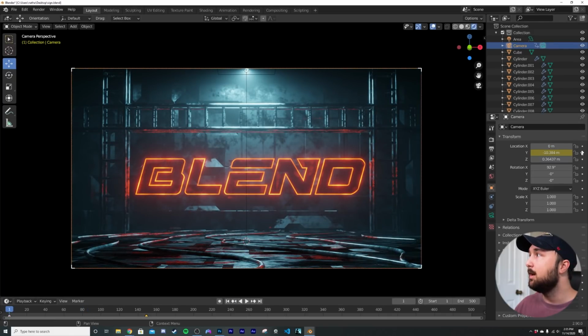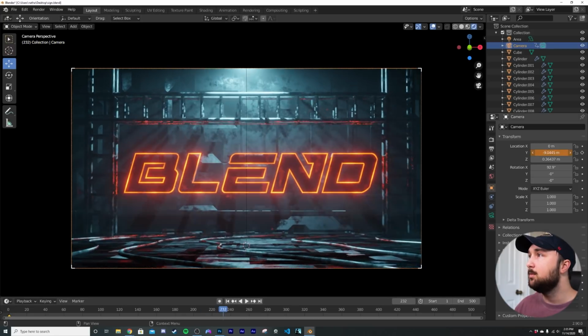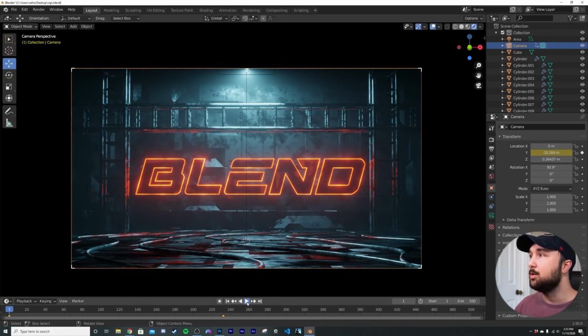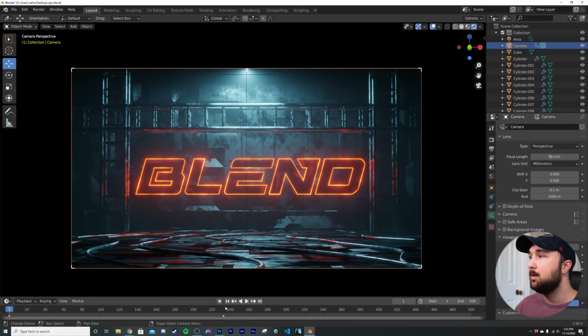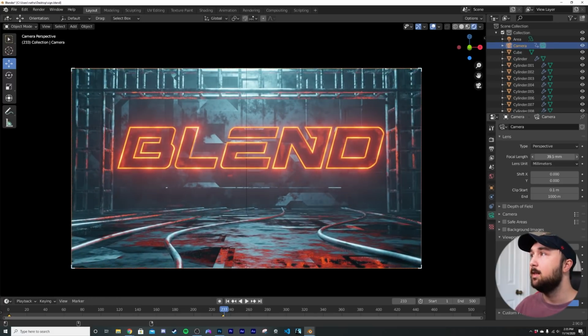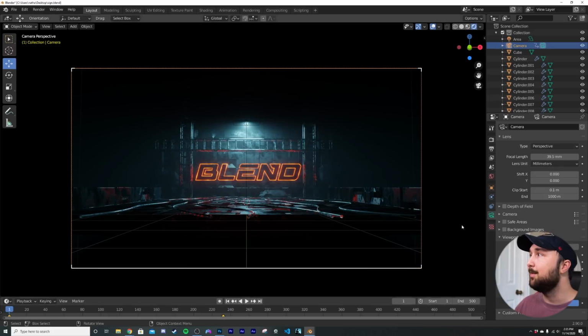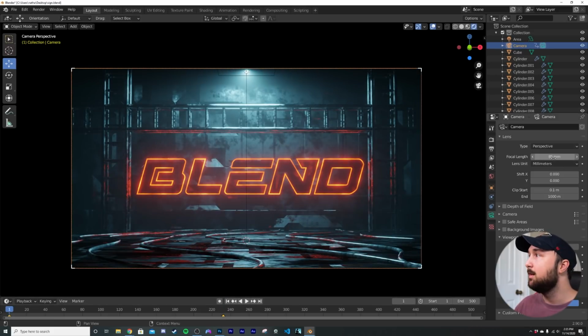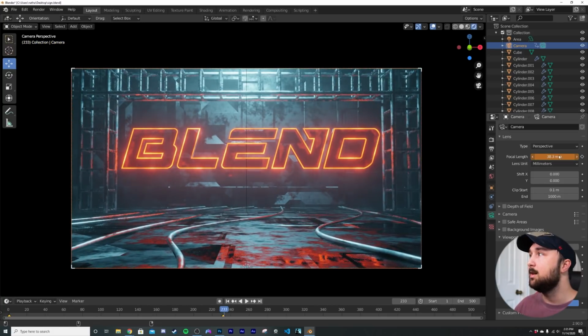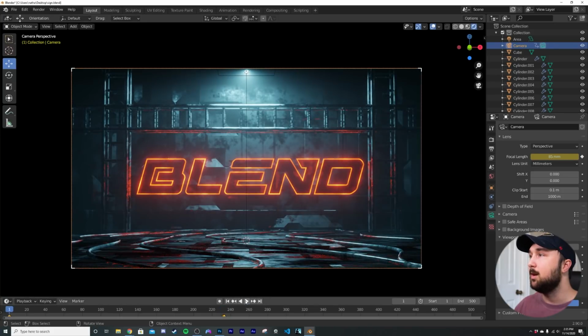So I'm gonna go back and I'm gonna redo my keyframing. So I'm gonna clear the keyframes and click that, go to around here, zoom really close into this, or something like that. And the closer you get, the more extreme the effect is going to be. Now let's click on the camera's focal length area, go to the end, and I'm gonna bring my focal length out like this. And then, oops, I forgot to add my keyframe. Let's go back 85. Click that, go to the end, bring that focal length till you like how wide it is. Click that, and then let's go.